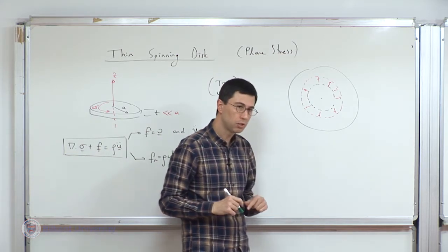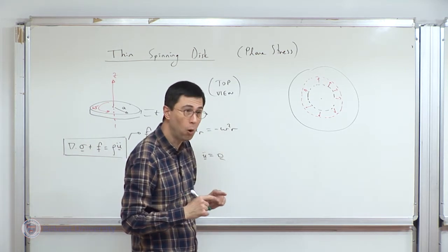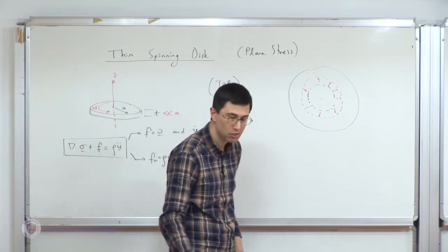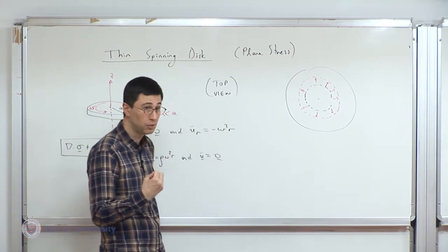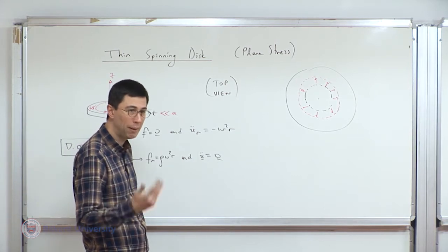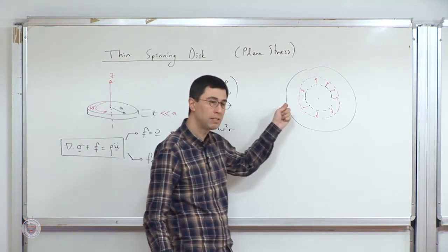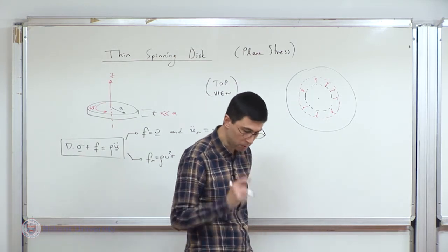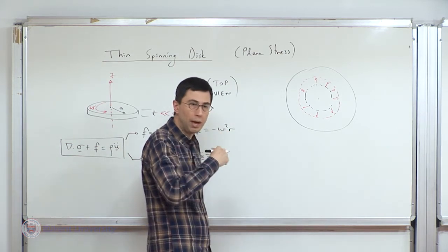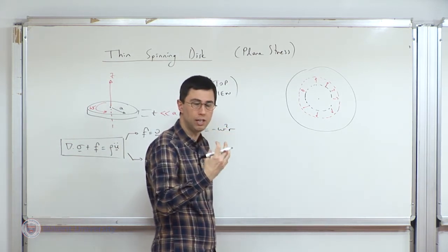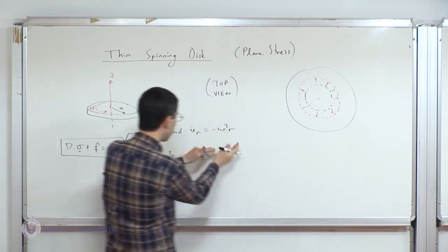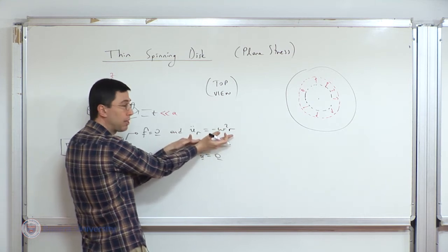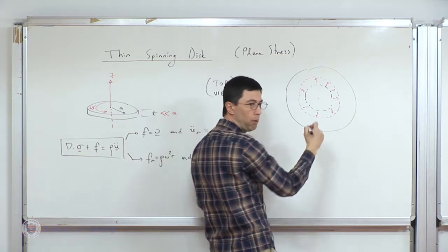But we know that rigid body rotations do not cause strains if they are small. In this case, it's not small, it's very large. So if I do my small deformation analysis, I will eventually get a strain out of it, which is not physical. It shouldn't be there. It's not compatible. The idea of a large rotation is not compatible with a small strain analysis, as you have noted in one of the homeworks. So instead, what I'm going to do is to eliminate that rigid body rotation, which physically I know that the inertia part is already in here. So this inertia due to rigid body rotation is going to cause stresses, and I'm capturing that. But the actual rotation of the points, I'm not interested in.